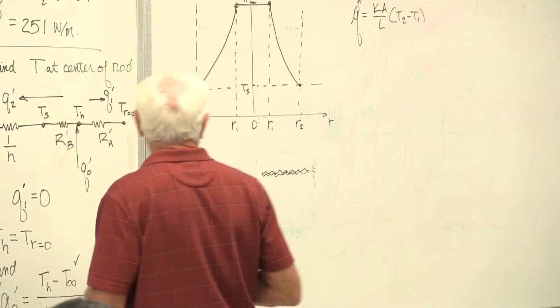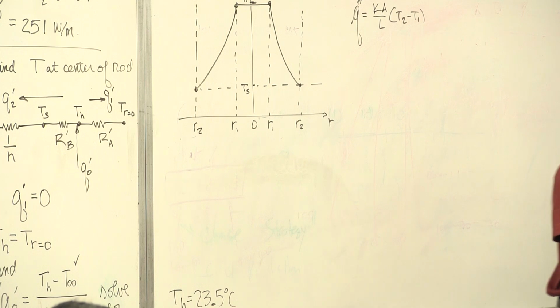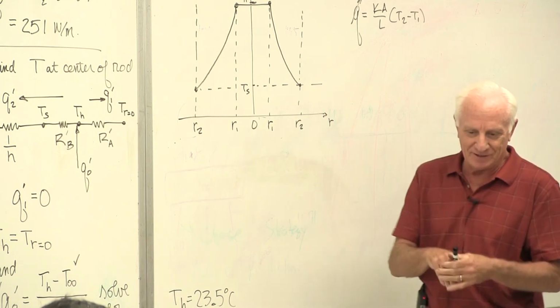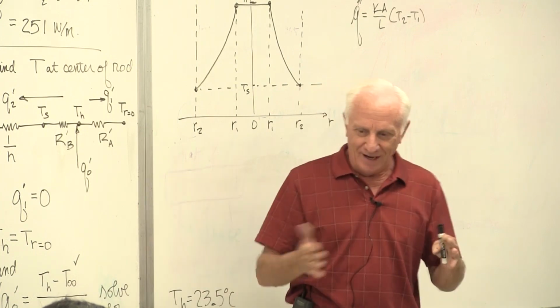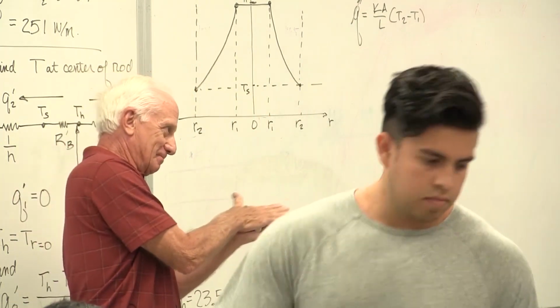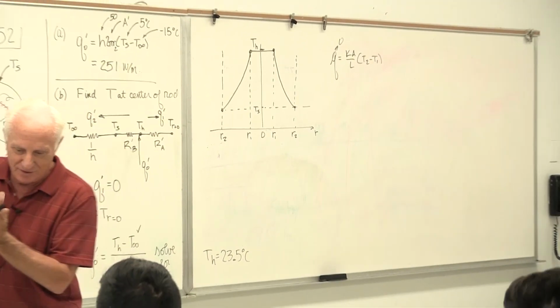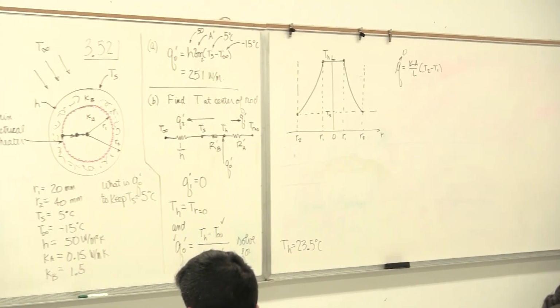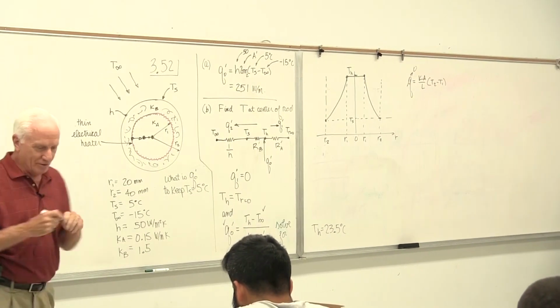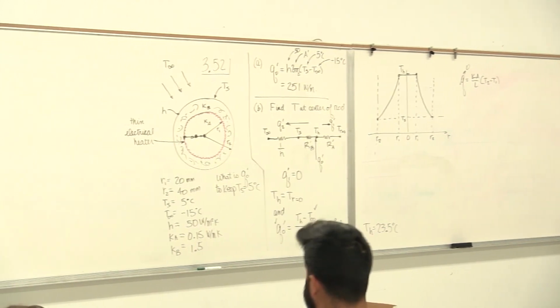So, if you have two really fine polished surfaces, very low contact resistance. Take a rough concrete surface like on a freeway and a piece of sandpaper, oh, there's a big contact resistance because there's a lot of little trapped air in there, and that trapped air gives a resistance to conduction heat transfer. Okay, now we're going to go over to the last part of chapter 3, which is extended surfaces.